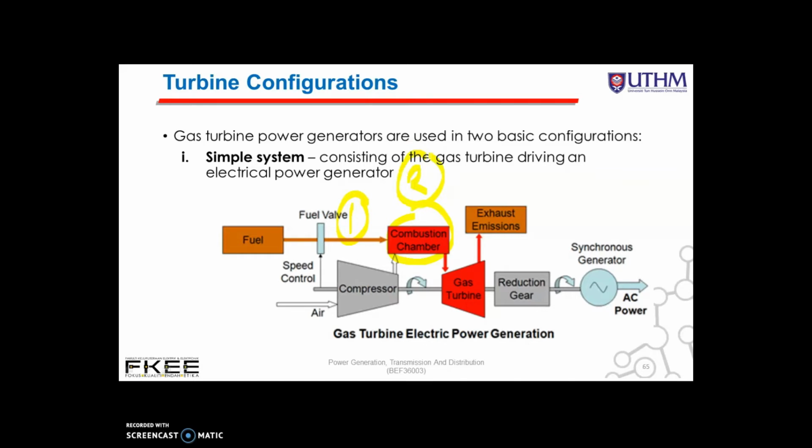It is typically made up of a ring of fuel injectors that inject a steady stream of fuel into the combustion chambers where it mixes with the air. The mixture is burned at temperatures of more than 2000 degrees Fahrenheit. The combustion produces a high temperature, high pressure gas stream that enters and expands through the turbine section.